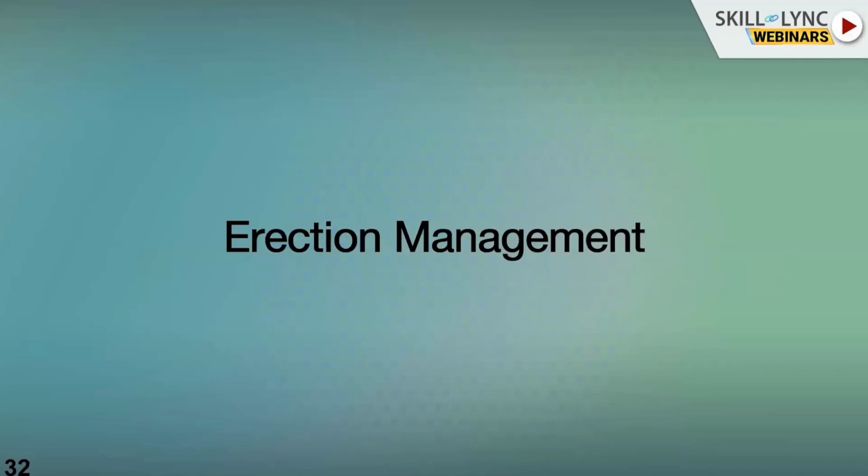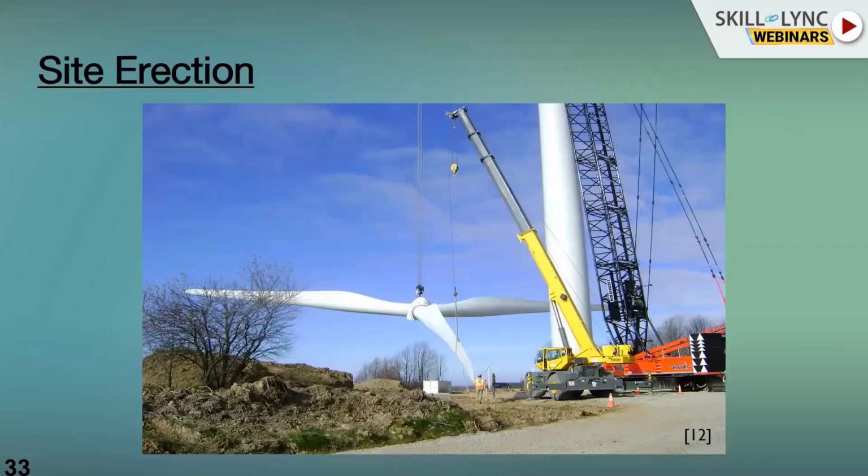And after logistics, erection. As I told earlier, it is not possible to do erection throughout the year. It is only possible in low wind. We have to see the low wind condition, and also rain, mainly wind and rain. During rain, it is not possible. Lightning too, because they are working at a height of 80 meters. After installing all the equipment, the lightning protection system, everything will work. So we have to give safety to the person. In case of rain and lightning, the erection and commissioning activity is not possible. Because of these reasons, erection management is also critical. So these are all the erection of the main components.